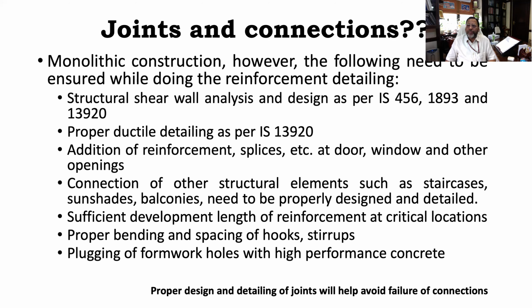Also, connections: because it's a tunnel formwork, you are making the walls with this. So the other structural elements such as staircases, sunshades, and balconies need to be properly designed and connected to this walling system, and that can be done easily by connecting through double bars and having sufficient development and lap length. That is very important when we are working with tunnel form or monolithic concrete construction.